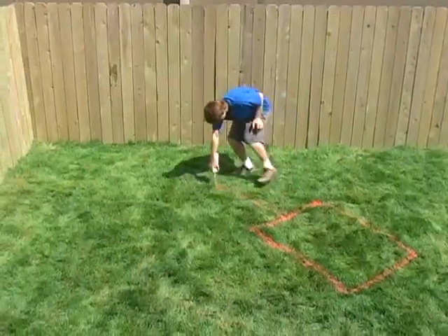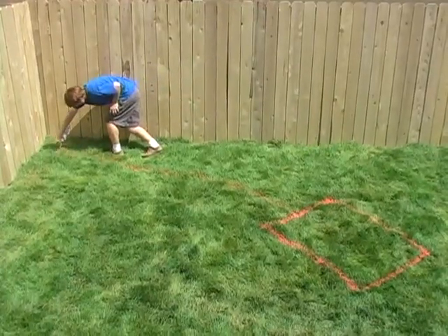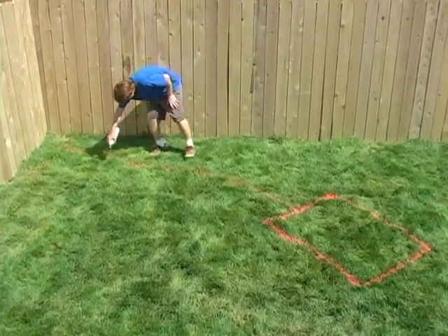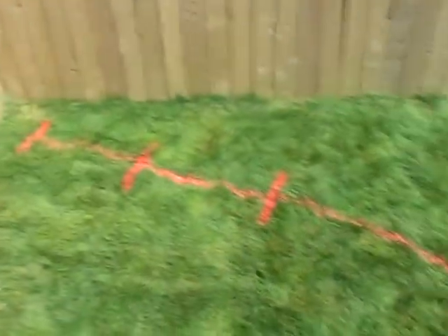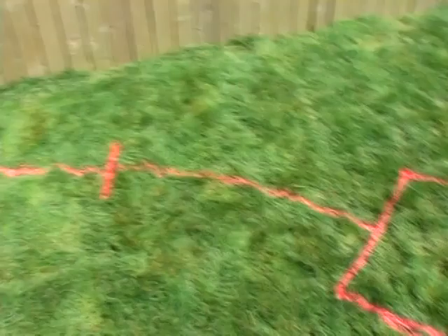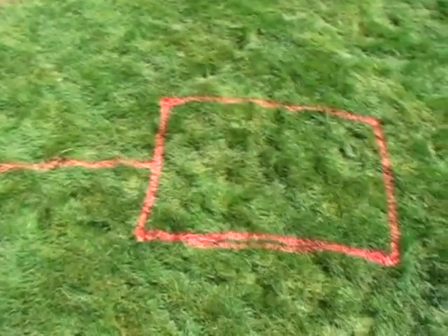Now we're going to mark out the watercourse with our paint. We paint marks at several places between the basin and the top of the waterfall. These marks indicate the placement of cascades. You can place your cascades anywhere along the watercourse.